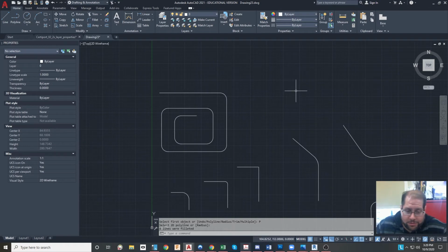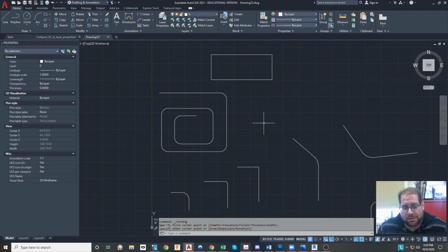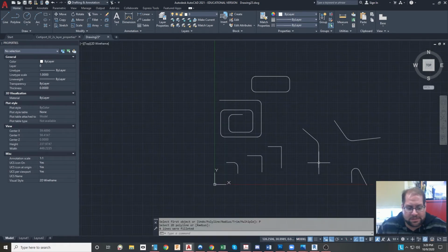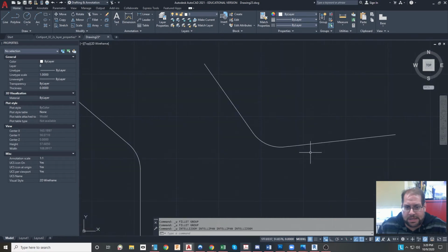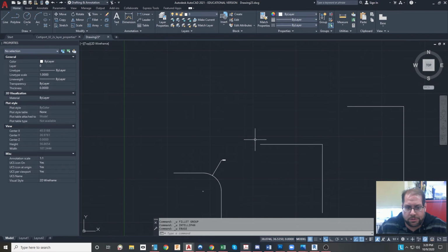So it's a quick way to do all of the vertices inside a polyline or an object with multiple pieces, like even a rectangle. A rectangle has 4 vertices associated with it, and if I do a fillet command with that polyline, fillet on, it'll do all 4 of them and make a nice rounded rectangle. So that's fillet. Chamfer is a little bit the same. I'm going to reset all of these using undo.